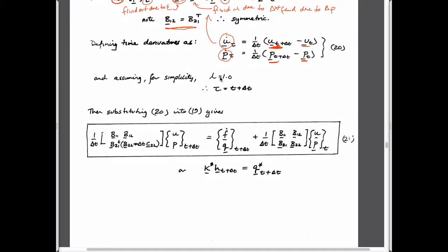It contains lots of things that we know. It contains our stiffness matrix, our body force matrix, our squeezing out fluid from the sponge by strains, changing the volume of the fluid by changing the pressure, and it contains our Darcy flow matrix, which we all know. It contains these things that we don't know that we want to solve for.